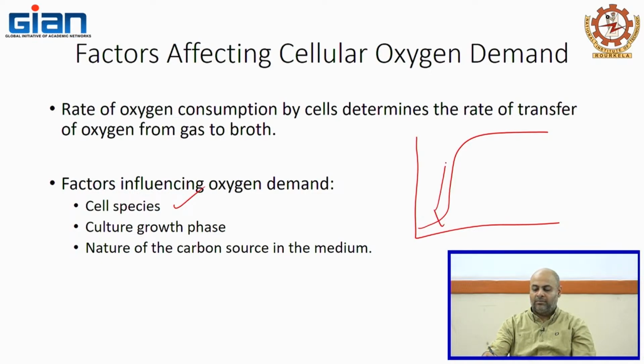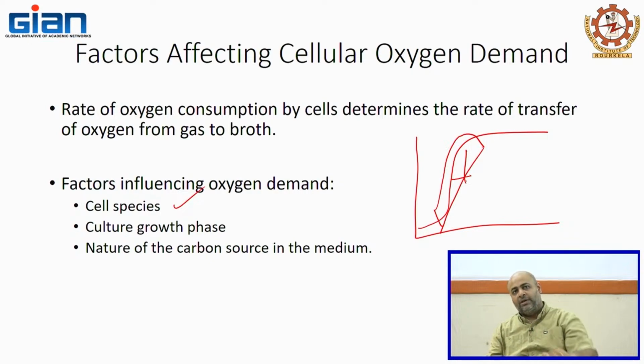The early growth phase to the exponential phase, where you have the constant growth going up. Your oxygen demand is high. You need it, as it is doubling, right? At this particular stage, when it is trying to acclimatize, you might not have a very high oxygen demand. But the moment it will start dividing, the oxygen demand will shoot up. And you have to make sure during that period, you're providing an appropriate amount of oxygen into your bioreactor.